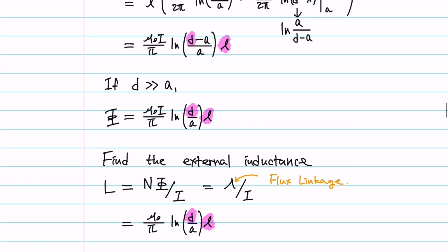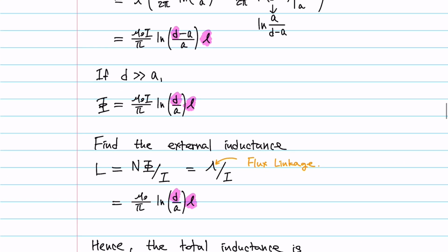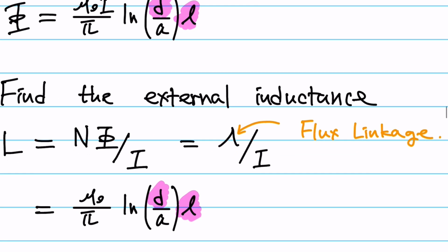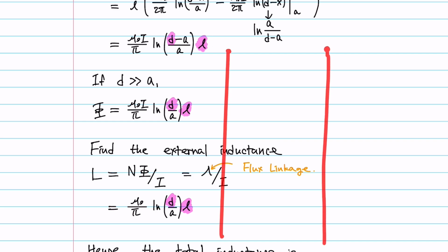And so you'll notice that the inductance between two wires will increase if you have a greater distance between the wires and if you have longer wires. So if you want to minimize the parasitic inductance, an inductance typically that you don't want, then when you design a circuit, let's say you have a PCB board with current traces, you have one current trace, then you better make sure the next current is not that far away.